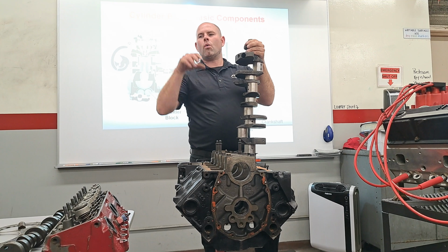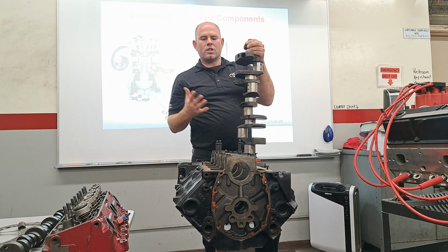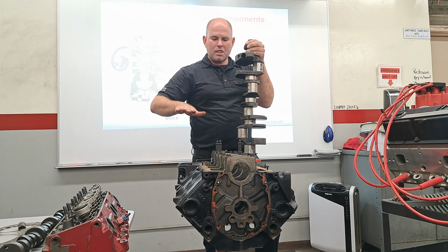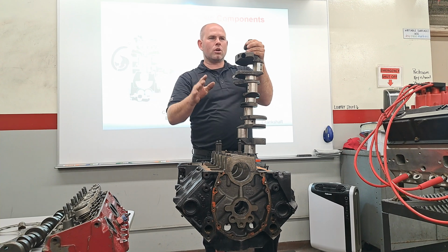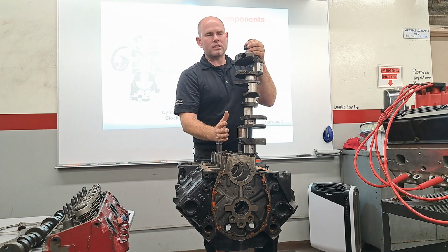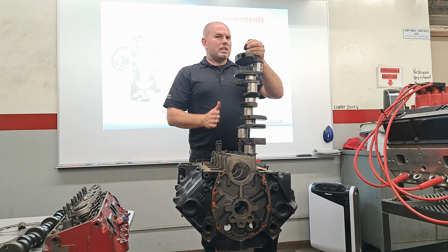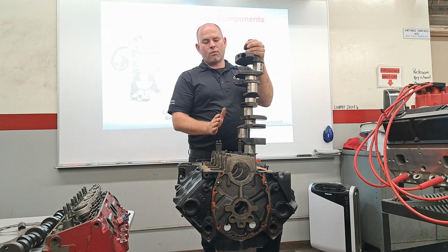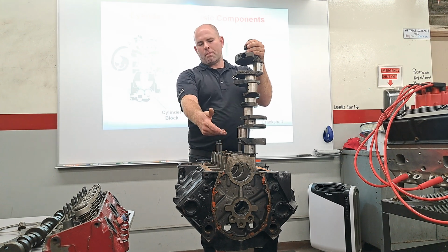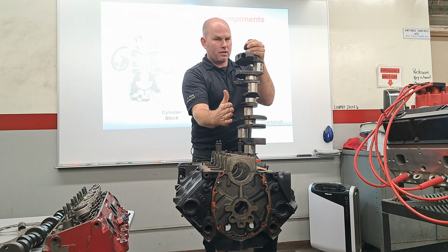Kind of makes sense? So this is going to be basically riding on the mains. And as part of the block, we'll actually call those the saddles. So all those main bearings are in saddles. Do you think they all need to be in line? All centered and stuff? Yeah. Definitely. Now, if we had a problem with one of those, we'd actually pop all this apart. We could lay a straight edge down in there, and we can see all the mains in line.